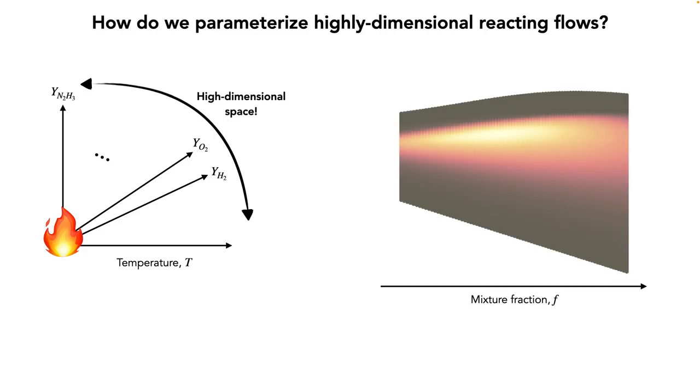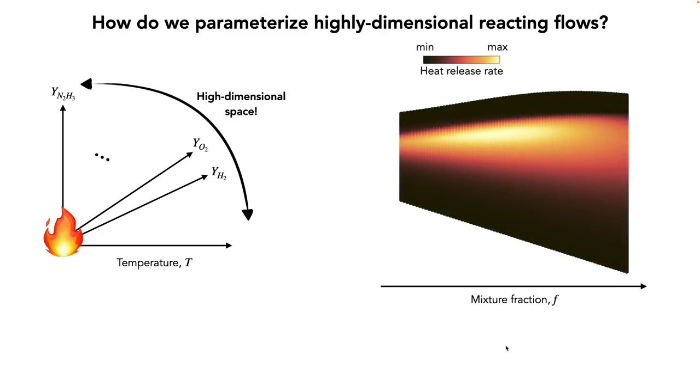For non-parametric systems, one such good candidate for a compressed parameter is mixture fraction, which only looks at the local stoichiometry of the flame, but does not look at any other effects, such as heat transfer, for example. Therefore, this parameter is usually necessary, but not enough, because for a single value of mixture fraction, the flame can be in vastly different states of reaction.